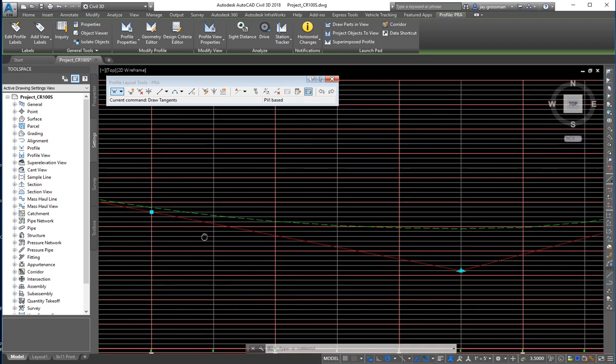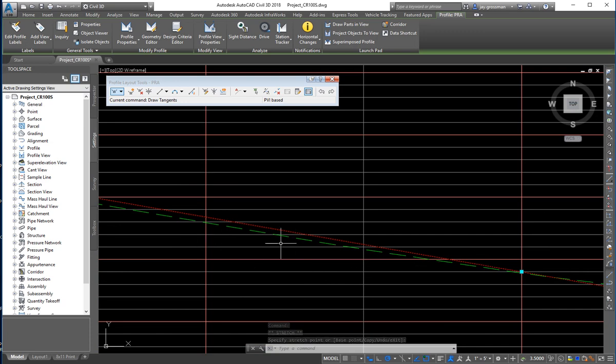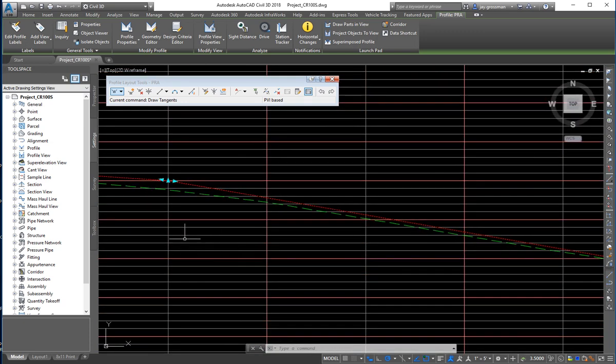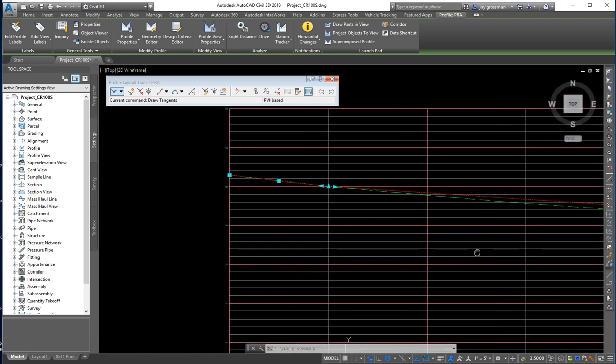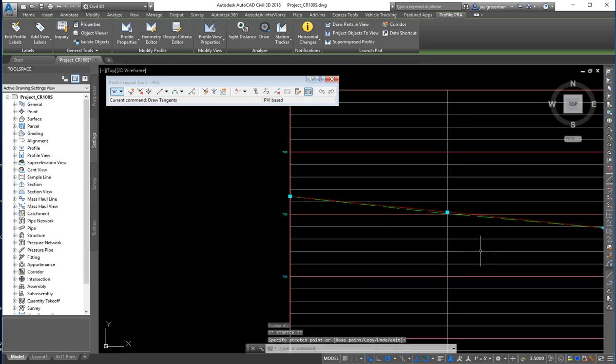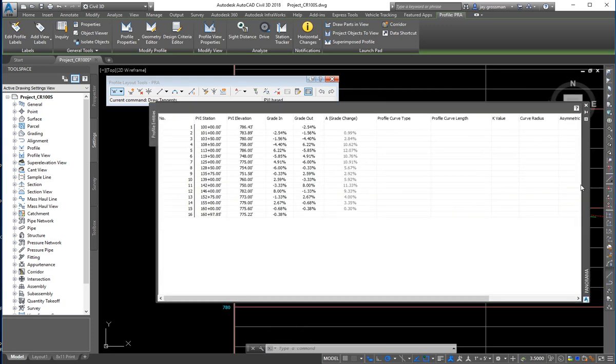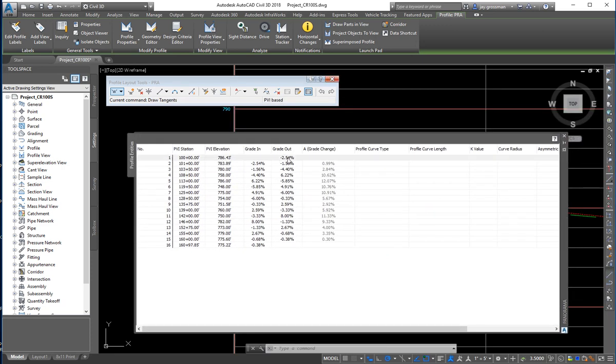And I would say this needs to go up a little bit. Let's go up 2 feet. There we go. And so right in here now, we're doing pretty good. In general, it's a little better to be high than it is to be low when you're out in this neighborhood. And we did have to change that. I'm going to move this PVI point down here. All right. And that should tie in pretty carefully. And if I come back over here and look at it, all right, oh, I'm not negative 2.75 anymore. Now I'm at negative 2.54.